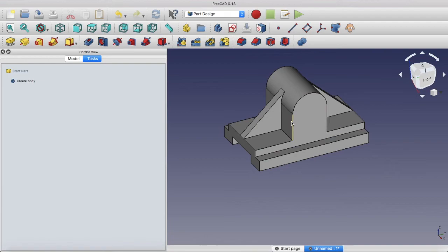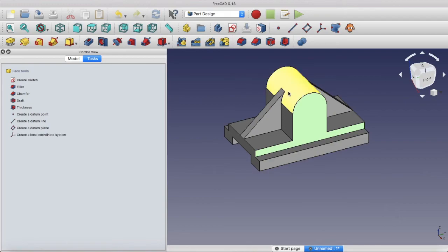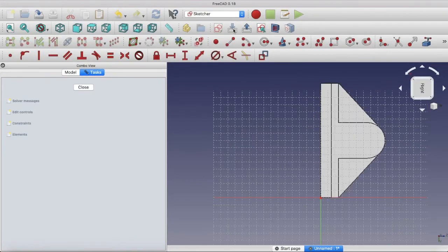At the end, we will make a hole on the body of the second part as per the model before we close our assignment. For that, we click the desired plane on which we want to make the hole. Click the tool to create a new sketch again.